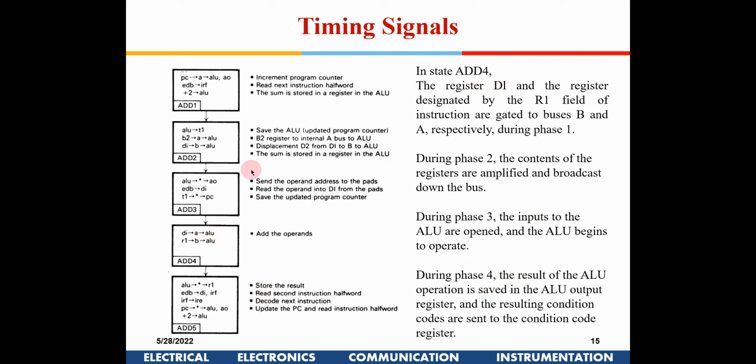First the data will be placed, in the third cycle the data will come to the ALU, and at the end of the fourth cycle the data will be available here. So all 4 phases will be used here. Now in the final one, from the ALU the contents are being updated into R1 here.